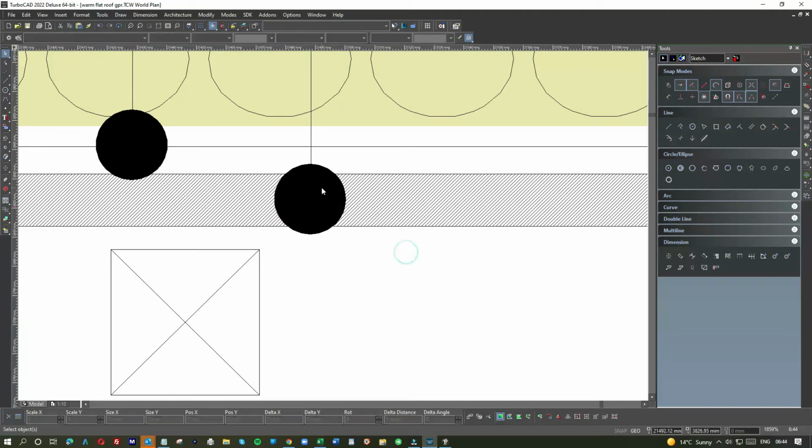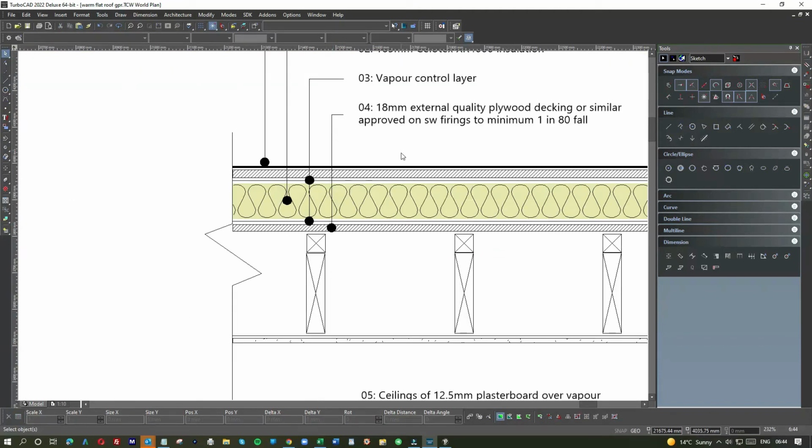We generally use 22, and the reason for that is you want a board that's sturdy. And if you don't fancy using ply, then you can use interlocking board, which is 2.4 by 600, and it interlocks, and it's the green one. It's suitable for the outside. But because it's interlocking, it means you don't always have to cut it over a joist and screw it down. But that works as well as the ply.